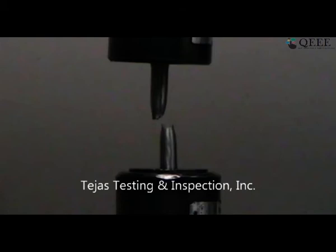Now you have two materials here. One is steel, one is concrete. The behavior of concrete is brittle. The failure of concrete is brittle in nature. The failure in steel is ductile in nature. Naturally, if concrete fails first, then what happens? This fails suddenly. So therefore, we really don't have any time to take any precautionary measure.